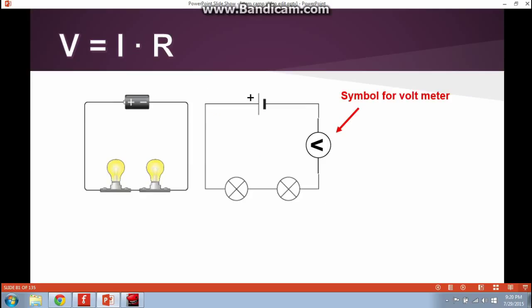So let's move on. One thing I want to talk about is measuring voltages, because remember, that's how we read signals in the analog world. We want our Arduino to read voltages and do something with those signals, right? That's what signals are. For at least our purposes in this camp, signals are changing voltages or changing pressures or changing electric potentials. However you want to say it, it's changing voltage.